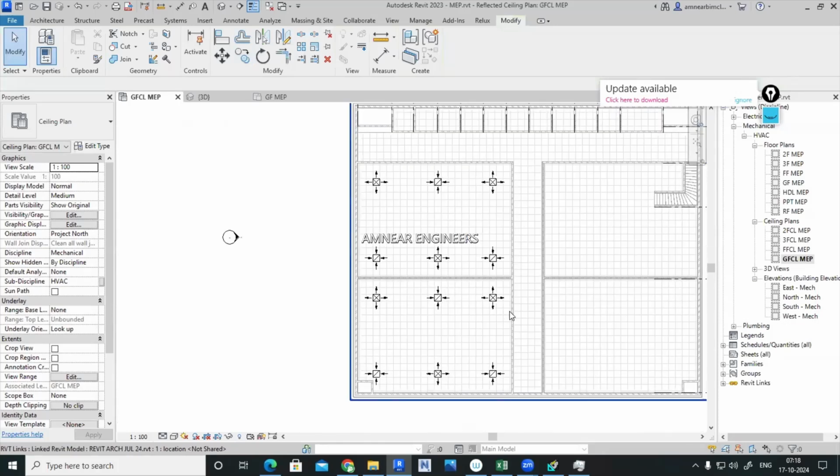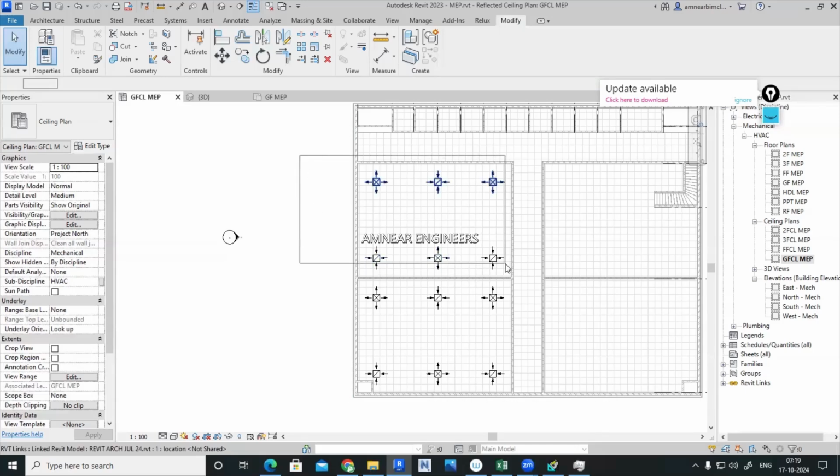Okay. Now we can do one thing. Since we are having a multi-storey building, this is ground floor, first floor, third floor, second floor. For this floor, I'll be proposing a single machine only. One machine. And with the help of VAV boxes, I will be planning to serve both the spaces. See, I did the heat load of only this space. The same way, heat load of this space also has to be performed.